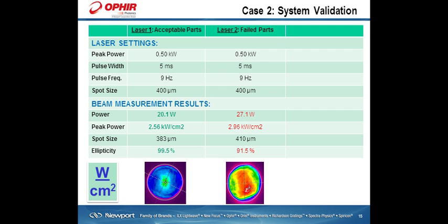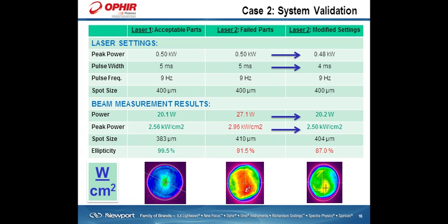You see, just visually looking at the two, you can see that there are two very different laser systems being applied, even though they're of the same OEM and the same model number. So we did some experimenting, and over the course of about a half hour or so, we just played around with the laser parameters. All right, we decreased the peak power, we decreased the pulse width.